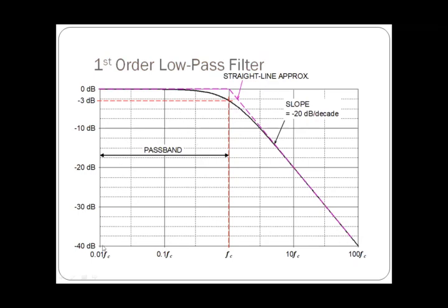So it allows the low frequency signals, that is around from 100 Hz to FC, up to FC it will allow. That is, so we have made the frequency scale which is multiple of FC. So 0.01% of FC to FC it will allow, and beyond that FC it will not be allowing the signal to pass through it. So this is the pass band. Only in this band it allows the signal.